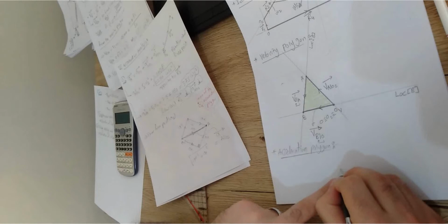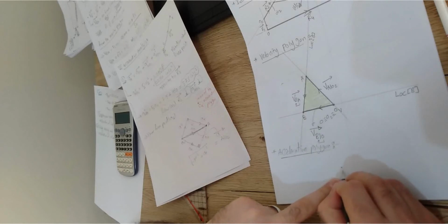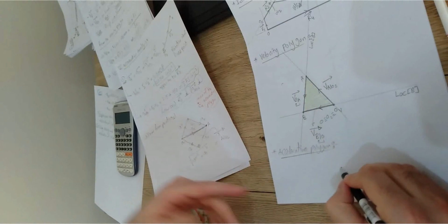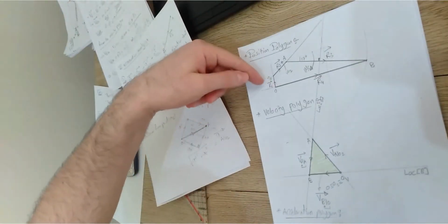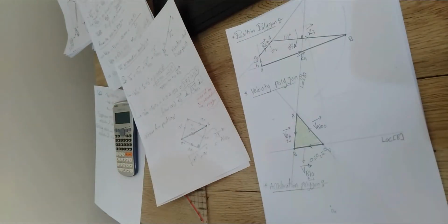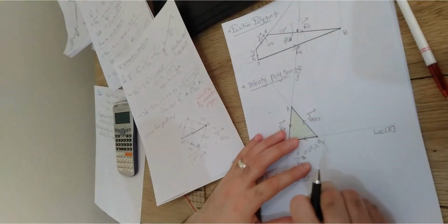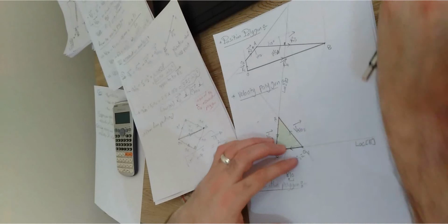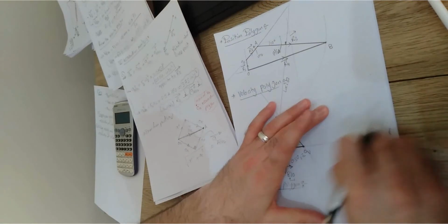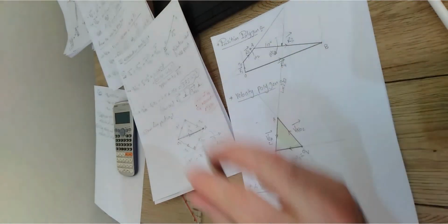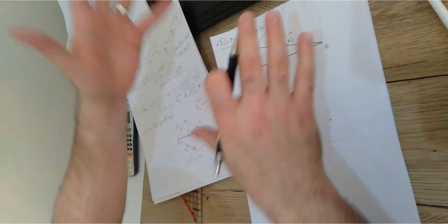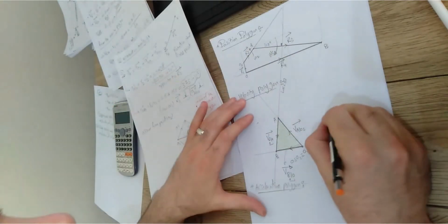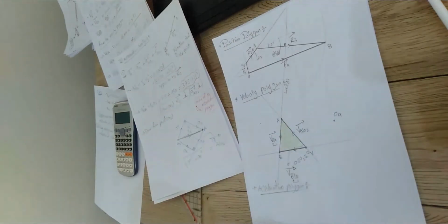So if I consider that OA, which is the origin point, the start point of the acceleration polygon, is at this point, and you start moving down opposite to the R2, as already given here, you aren't gonna find a space. That's why it is advised to start O2 at any point up there. You can even remove this one, and I can start creating the O2, and no problem if you have intersection between the different diagrams, that is fine. I'm gonna start with OA from this point, right?